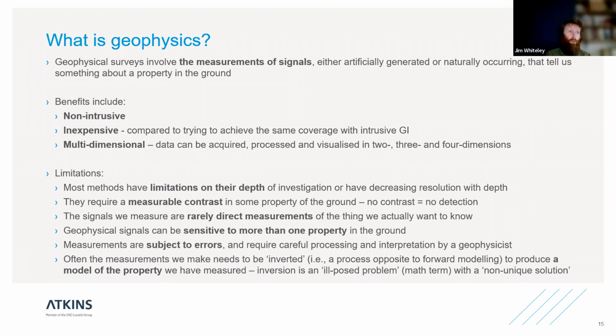So we can be looking at, for example, seismic velocity, which is related to the density of the ground, or we can be looking at measurements of resistivity, which is coupled with various parameters of the ground, including the clay content and also the degree of saturation as well.